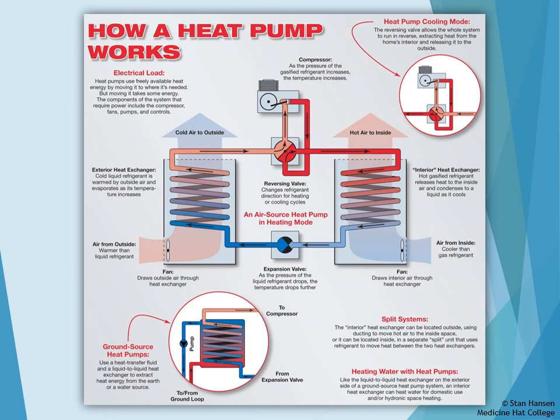It will require a four-way reversing valve in order to control the refrigerant direction to switch between the heating mode and the cooling mode. Some of the main components that we see in air conditioners are the outdoor coil, the indoor coil, the compressor and the expansion valve. We also have that extra four-way reversing valve to change the direction of the flow of the refrigerant. We also need to have a double active thermostat to control both heating and cooling, a sequence timer to make sure everything is working in the proper order, and a defrost timer just in case things do freeze up.